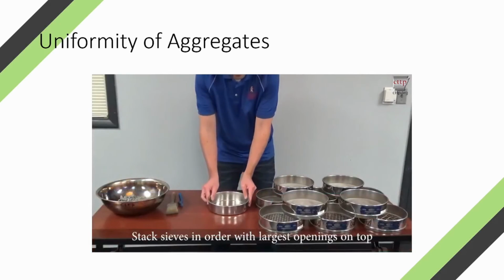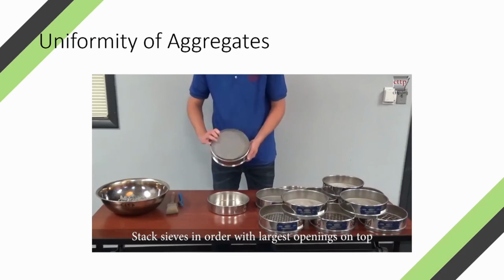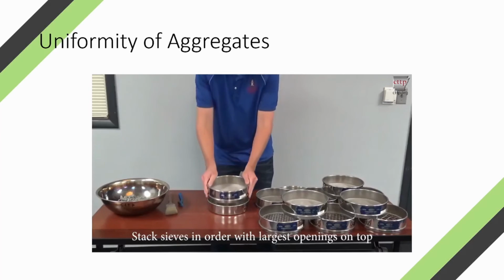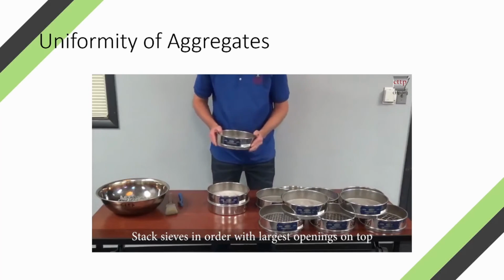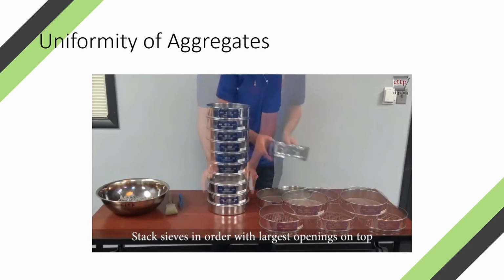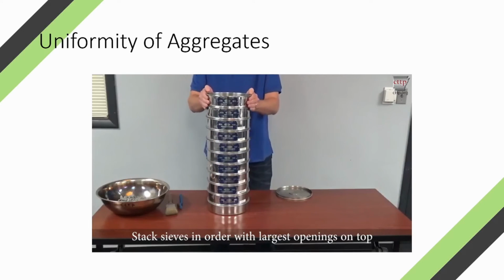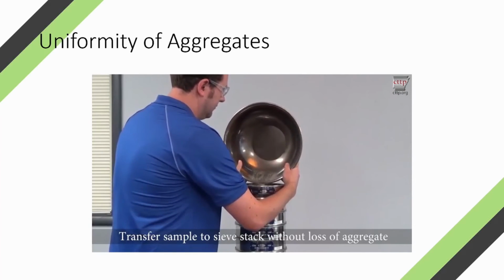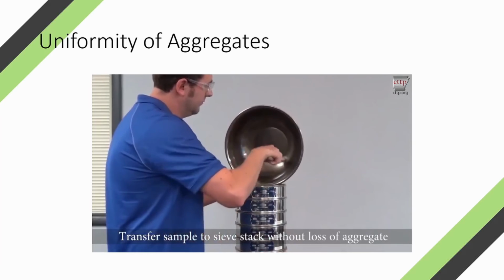Stack the sieves in order, with those having the largest openings on top. Transfer the sample to the sieve stack without loss of aggregate.